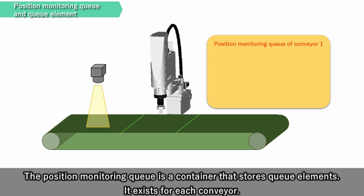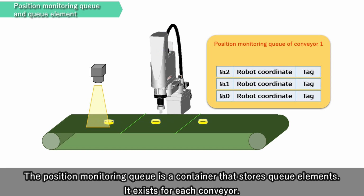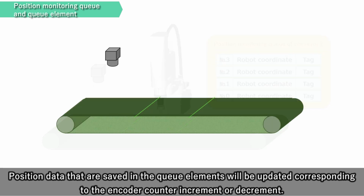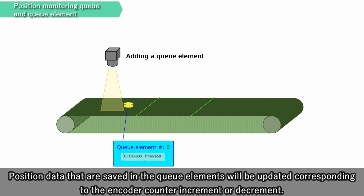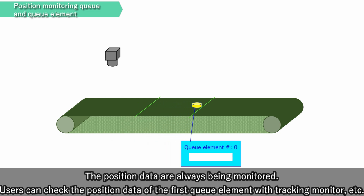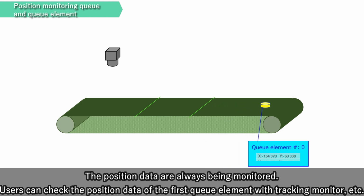The position monitoring queue is a container that stores queue elements. It exists for each conveyor. Position data and tag of workpiece is saved in each queue element. Position data that are saved in the queue elements will be updated corresponding to the encoder counter increment or decrement. The position data are always being monitored. Users can check the position data of the first queue element with tracking monitor, etc.